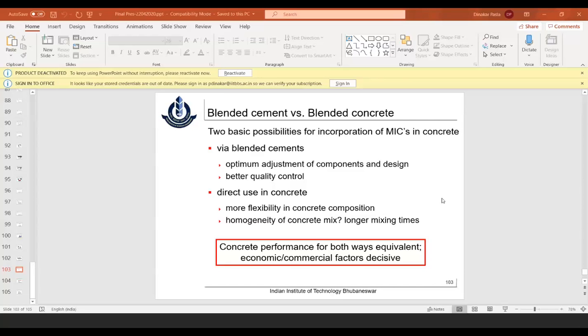Yeah, definitely it's changing. I think you also brought out that aspect of application-oriented concrete usage based on which cement has to be supplied. That is very important because our experience also shows when we were supplying to various RMC units in various cities, they were in fact transporting concrete. In some cases, they wanted slump retention of up to 2 and up to 3 hours as well. So we needed to have a kind of cement where cement and admixture are very much compatible, and they are able to get that slump retention. I think that is one of the most important practical aspects that we need to realize.